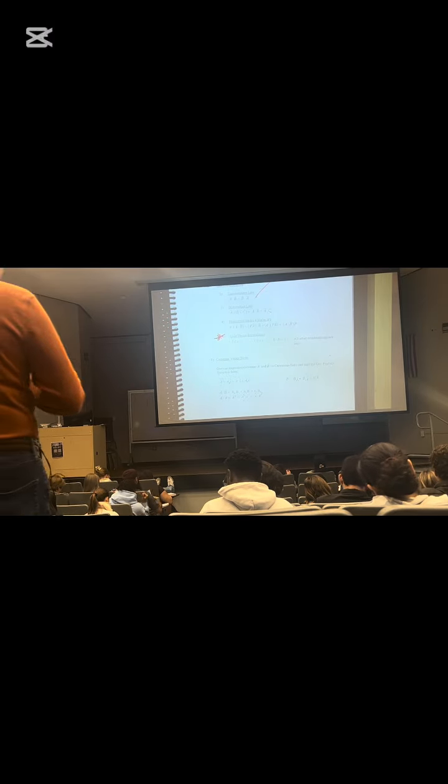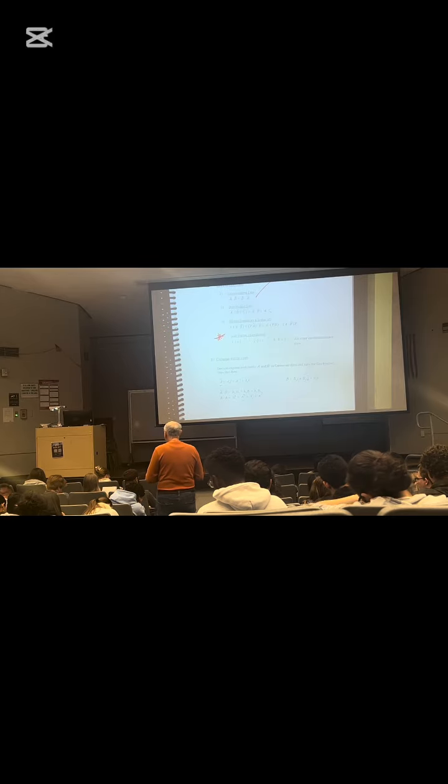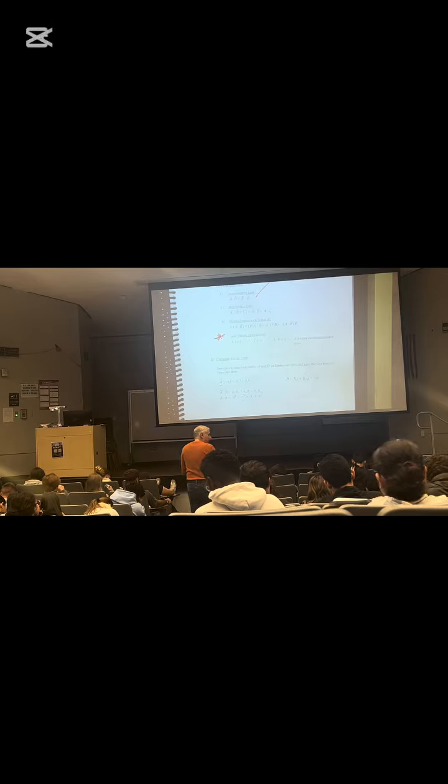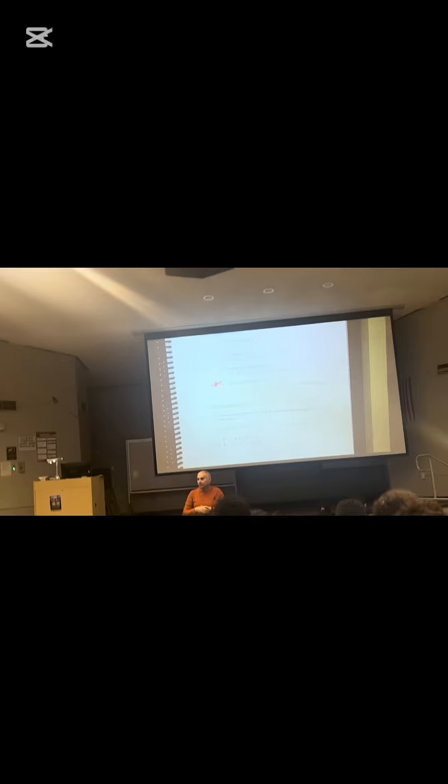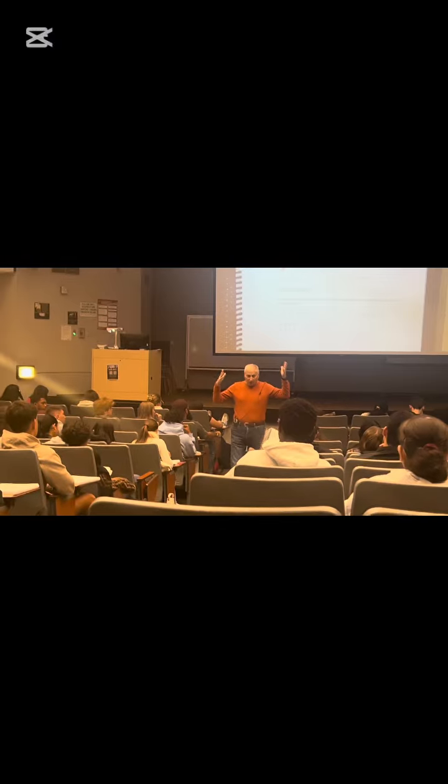The first use. Hey, what if I have 2 cables and I want to know the angle between the 2 cables? Well, if I have the position vectors of, say, RAB and RAC, if I want to find the angle between the 2 cables, dot RAB, dot RAC, divide by their magnitudes, take the cosine inverse, voila, I got an angle. That might be useful, because I might be looking at something and it's 3D, and you're looking at it going, it looks like it's 90 degrees, but I'm not sure. Well, I can be sure if I do this. Find the actual angle. It'll tell you if it's 90 degrees.